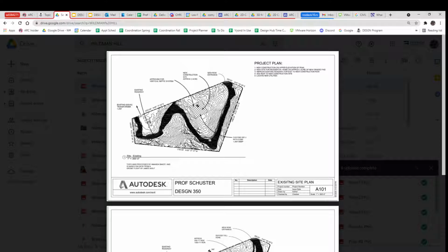And from Revit, we could place the road, do some excavation, look at how we would take this site and develop it for an existing or for a new construction property. So drones are really great because they give you XYZ, XYZ RGB. They give you all sorts of different formats of these point clouds. And this was a DXF of an elevation topo.